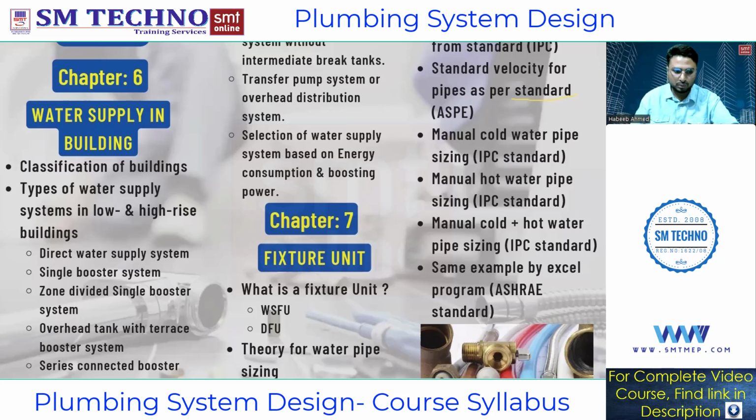Fixture unit, in simple words, is something you need to count, the fixture unit value, to proceed with pipe sizing. As of now, just remember this much. What do you mean by fixture unit, and what do you mean by WSFU and DFU? Fixture unit is a common terminology both in terms of water supply and in terms of drainage. So when I talk about the fixture unit, that is the specific fixture unit value.